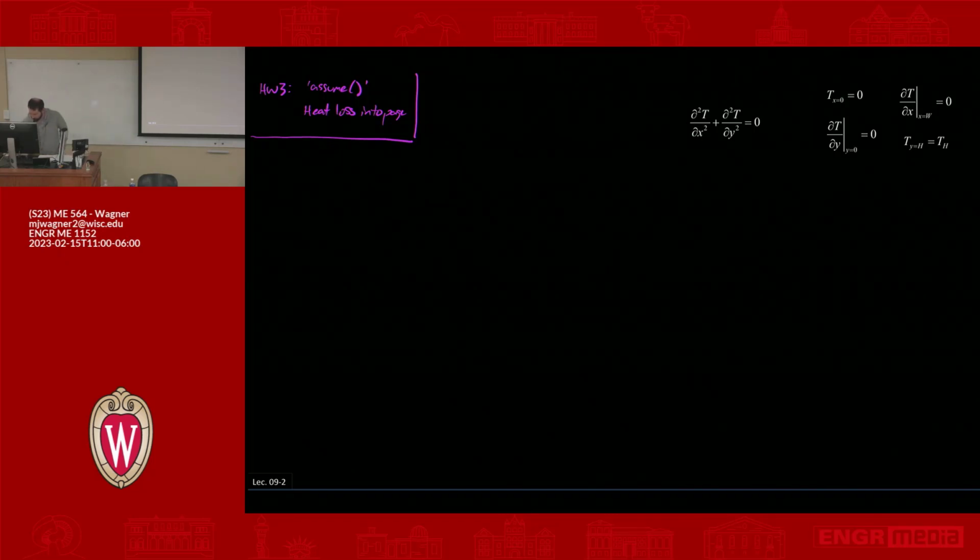I've written it kind of small here, but the idea is that in Maple you would say at the beginning of your program, any constants that you want to tell Maple are always positive, you would just say assume, parentheses, the variable name or the parameter name. So if you called that parameter A, it's followed by 2 colons, and then the quality, so positive. If you have multiple of those, then you say comma, B, positive, and so on. And that's going to force Maple to assume that those constants are what you want them to be.